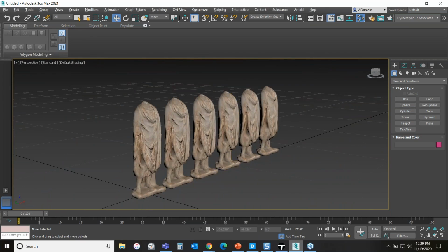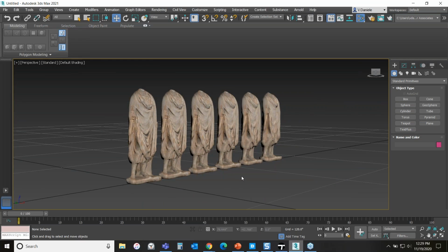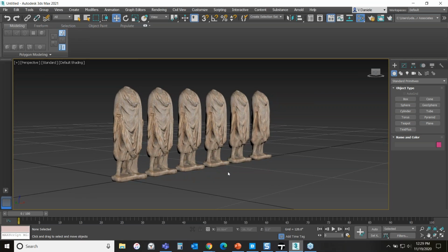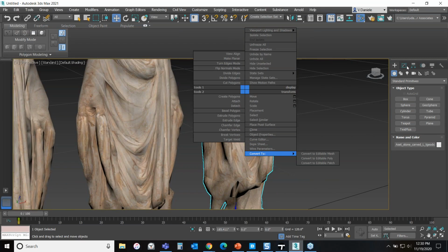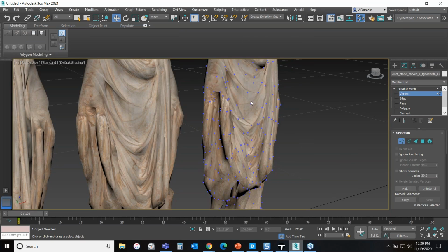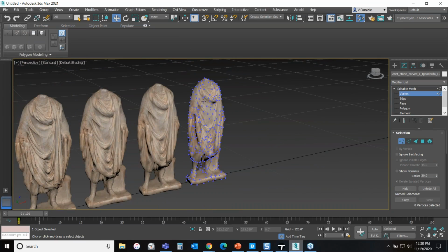So this is something we always want to keep in consideration when we're bringing in assets or when we're creating assets, to make them lower poly so that they perform better. Frames per second or frame rates are extremely important once you start building your VR projects. So this is something that you need to be aware of and pay attention to. Now, to go over into the next phase of actually creating the visualization from this stuff, one last thing I like to show here is that as this is a mesh object, it should already be converted as a mesh. I just like to show that once we bring it in, even as a scan, we do get those points, and we can manipulate it in a program like Maya or 3ds Max. We can start to manipulate that mesh and actually edit it too.